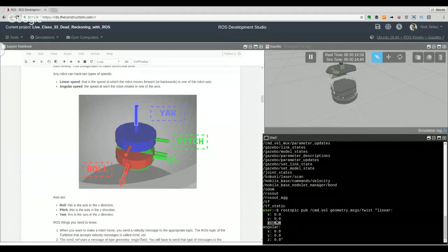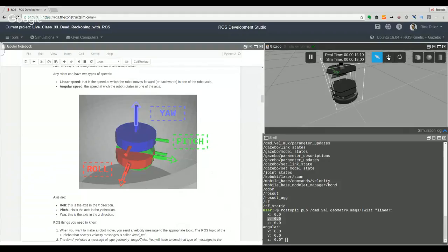And the exact same thing happens with a Y value. Why? Because you cannot move the robot to the side. So let me show you what I mean by to the side. I'm going to do, again, the hand of God. Then I'm going to see here the green. So this robot cannot move like this. Remember, it can only move forward and can only move rotating, and any combination of those. But it cannot move to the side. If you want to move the robot to this point, you have to rotate and then move forward.